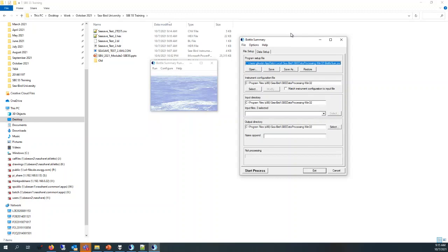You can use that to correlate the data you get from your bottle samples, the physical water sample that you're maybe running in the lab, with the data collected from your CTD sensors. That's good for calibration purposes. It's good for just lining up CTD data with parameters that you can't measure with sensors. And it provides just a useful record of the bottles you fired for each cast.